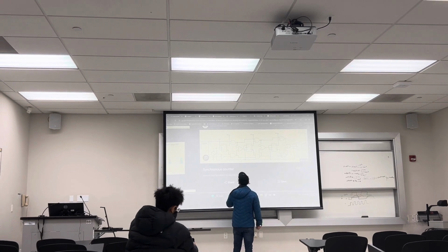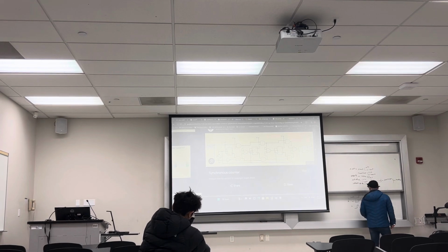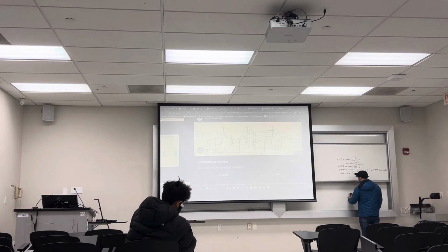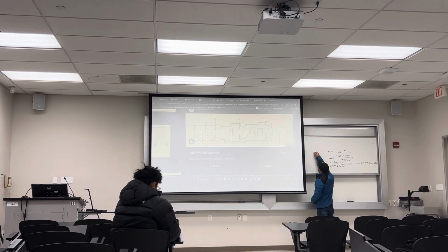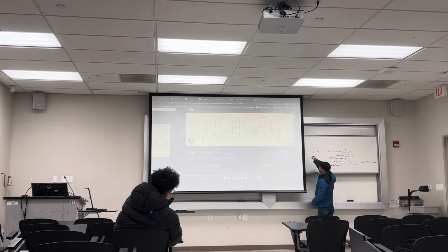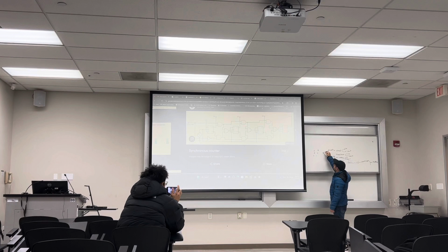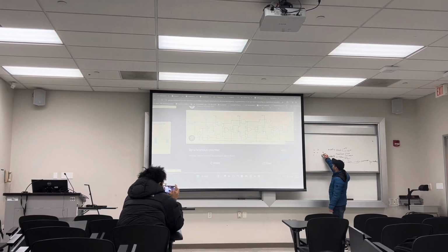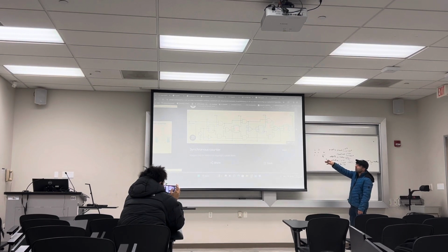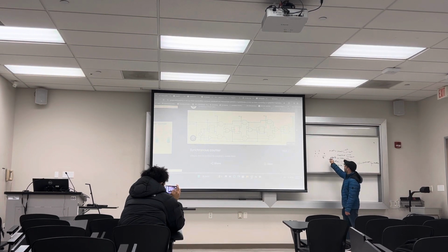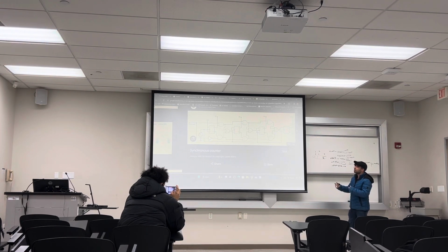How it works, look, the JK flip-flop inputs on this circuit are connected to VDD. When the inputs are connected to VDD, it means the JK flip-flop has only two conditions, J and K. Sometimes both are 0, sometimes both are 1. If both are 0, the output will not change. And if both are 1, the output will change, it inverts. So on this circuit, J and K are always connected to VDD, so you only use this condition of the JK flip-flop. And the output always changes when the clock comes to the circuit.